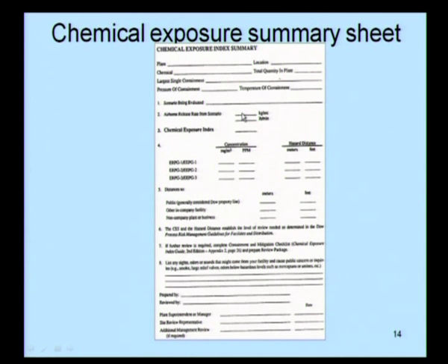Also, obviously I have not given you equations for non-SI units at all in my presentation. Once you get the AQ value for a specific type of scenario, maybe gas or liquid release, try to compute the chemical exposure index from the equations given in the previous presentation. For the chemical being identified, look at the ERPG guideline and try to find the concentration and the hazard distances. Try to obtain the concentration of that chemical in mg per cubic meter and enter those values here.